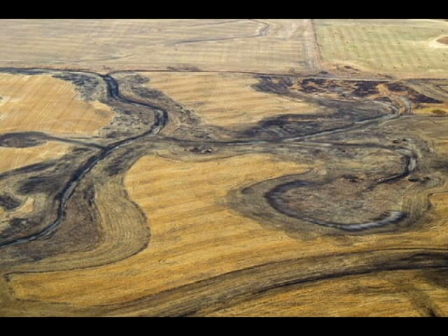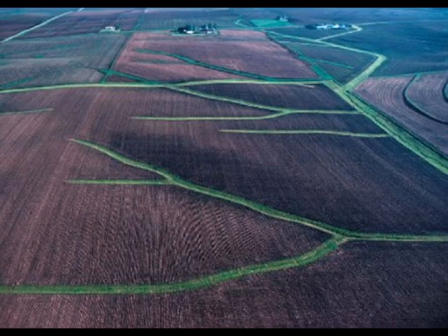On lands that require only surface water disposal, the drainage system should be built at the same time the lands are leveled, if possible. In many cases, the disposal system will use waterways designed principally to carry storm runoff. If irrigation tailwater is to enter these waterways, special plantings and maintenance often must be specified.